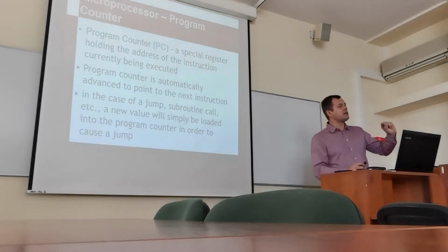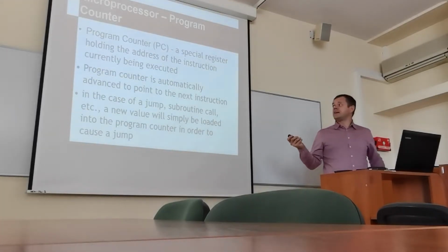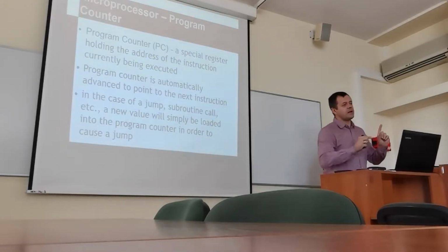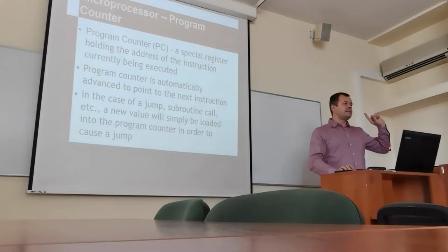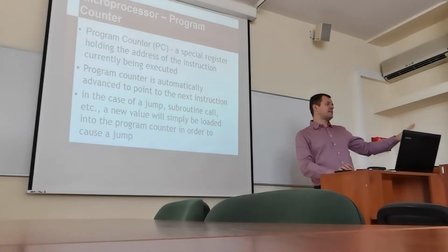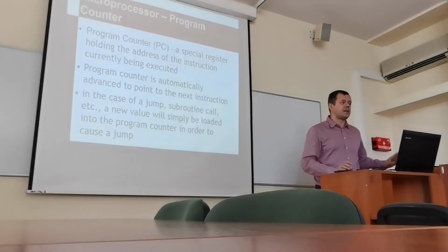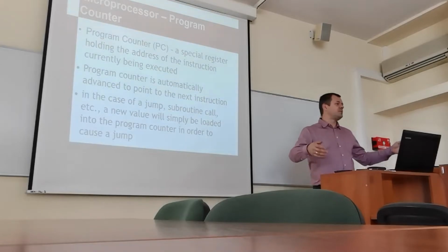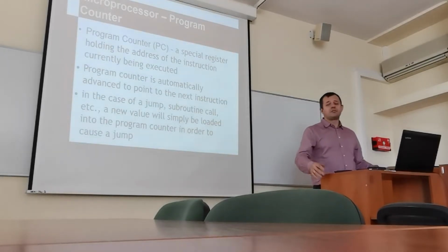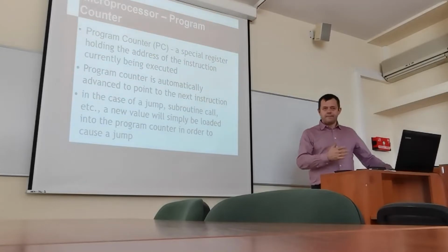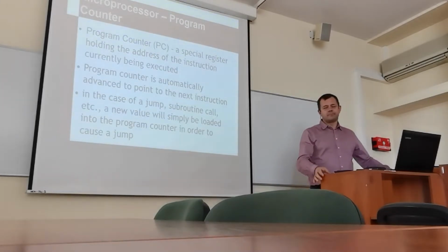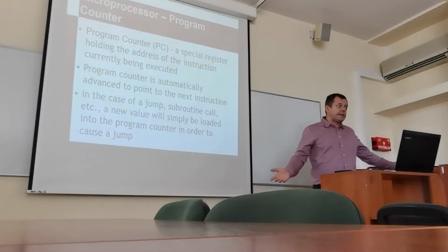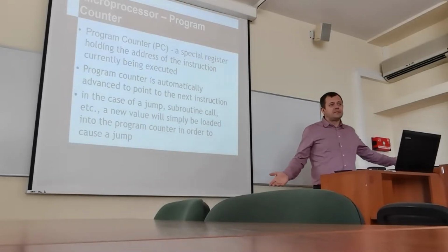So how long a program can be is defined by the width of the program counter. The width of the program counter is never as short as 8-bit. I have never seen a microprocessor that has an 8-bit program counter. The program counter is usually 10-bit, 11-bit, 12-bit, 13-bit, 15-bit. It's also very rarely 8, 16, or 32-bit width. It is in some microprocessors, but quite often we've got a strange program counter width, like 14-bit.